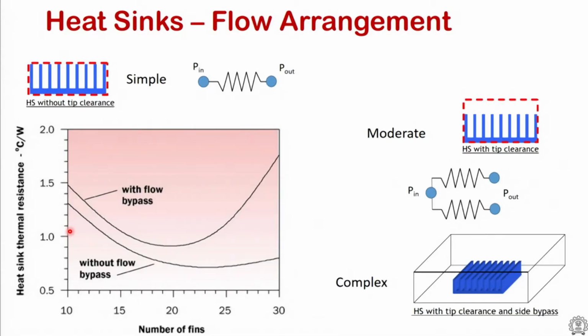So sometimes it may not be the pumping power of the fan that is always the metric. Sometimes it is the pressure drop, even though it doesn't have a direct energy metric to it. So one always operates, when you have these complex situations, the optimization for fixed pressure drop, or should it be fixed pumping power, will be decided based on the flow configuration that is being handled.